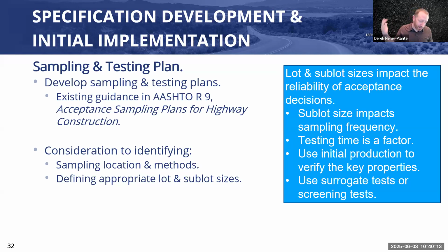Many agencies, we'll hit on this a little bit later, will do this because balanced mix design has shown that things our industry has maybe taken for granted with our current systems, we can't with balanced mix design. A perfect example: PG binder supplier or source, whatever you want to call it. If it gets approved in a mix design 6 months earlier, is that going to be the same binder that shows up on the job? It'll be anything but the exact same thing. And that's shown to have differences. You could say the same thing with RAP and other things.